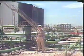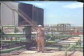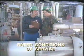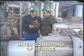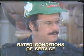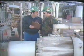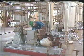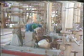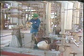Centrifugal pumps are usually selected for a given flow capacity and total head, or pressure capacity, when operating at a given speed. These conditions are called the rated conditions of service and are the conditions under which the pump should be operated for peak efficiency. If operated under conditions other than its rated conditions for long periods, the pump will be damaged and maintenance costs will rise. In addition, pumps should always be operated in accordance with standard operating procedures for starting and stopping the pump. Failure to observe standard operating procedures will result in serious damage.